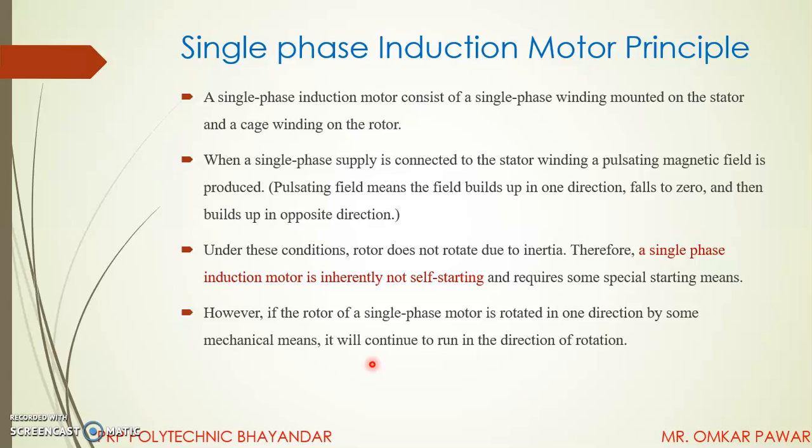Suppose the direction of rotation in half cycle is clockwise. At that instant, if we rotate the rotor in this direction, then that clockwise torque has a value much more than the anti-clockwise torque. So it will start, and vice versa.